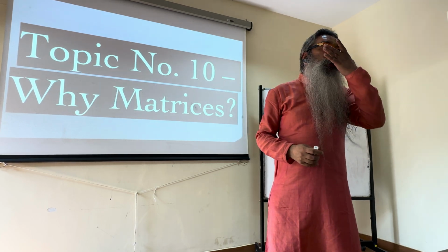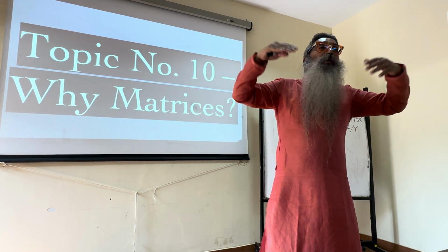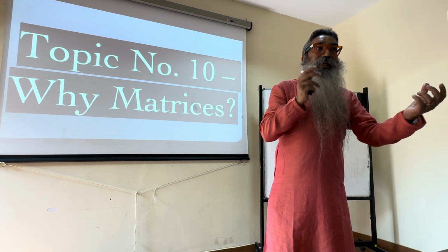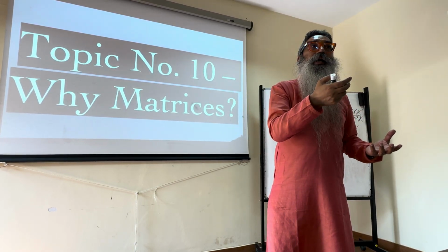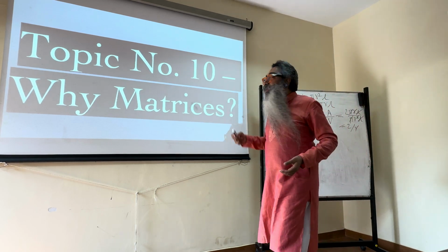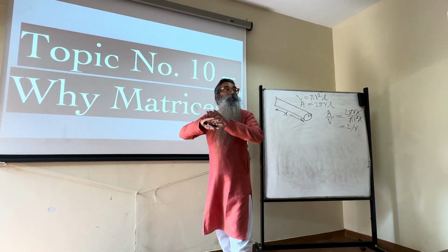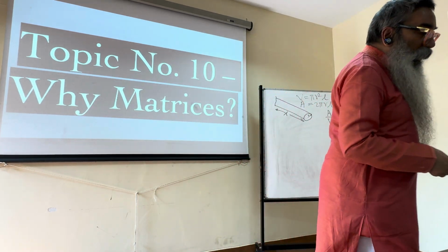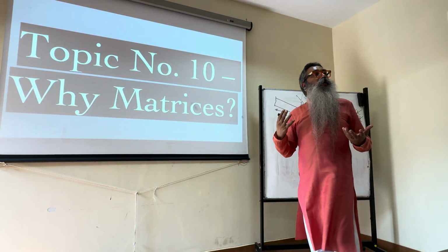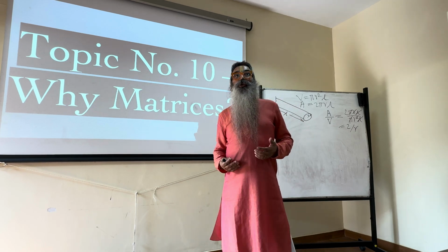Similarly for the tails, horizontal or vertical. So all of those you want to maintain in a particular way. Yes, there are transverse ribs to do that, but within the material, if there is something that can be done, well and good. And matrix, once it is solidified, obviously retains that shape. So that's a very, very important property. Anything else you can think of about a solidified resin? What are the advantages it brings to a structure?